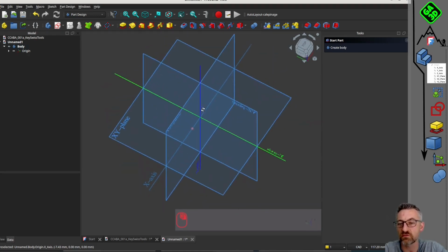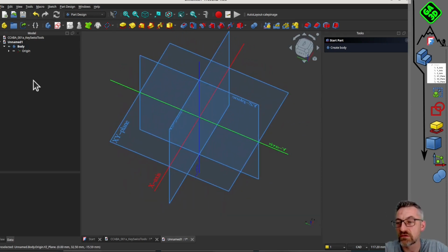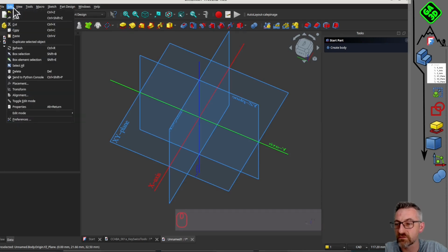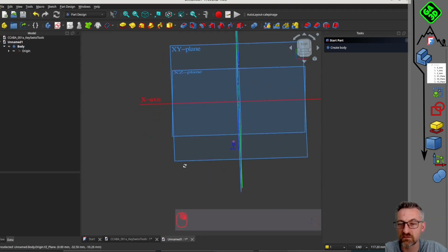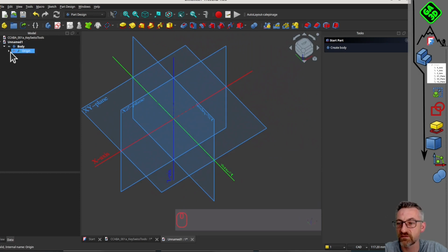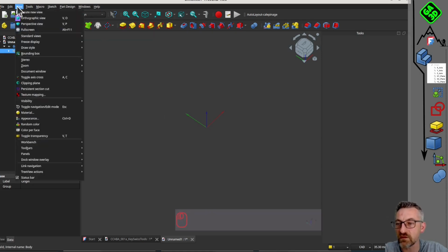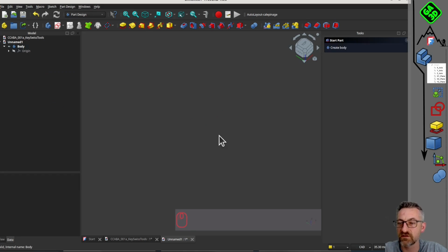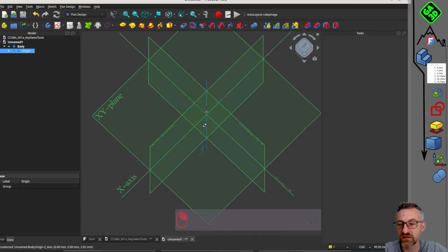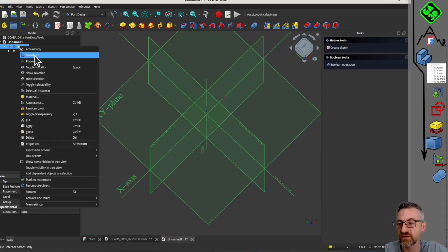So we'll hide the body references, which is really the unique reference, the 0 in the 3D world of FreeCAD, and so you can display it by simply going here, View, Activation, Deactivation, and at the level of each body you create. In fact, you will be able to move them relative to the universal origin. So, how do you do that? Right-click, Transform. There, a magic tool appears, and then you can move it back to the center. So we do it like this.